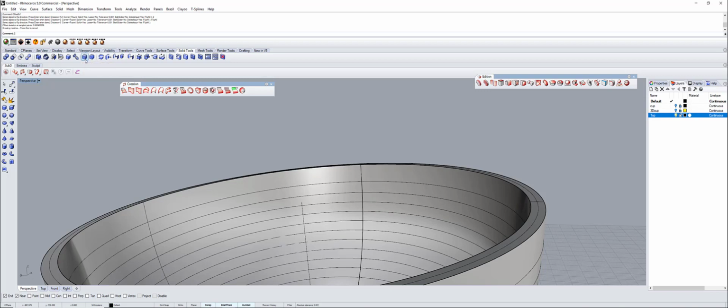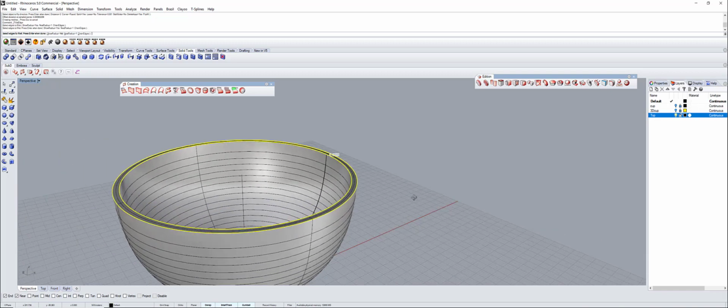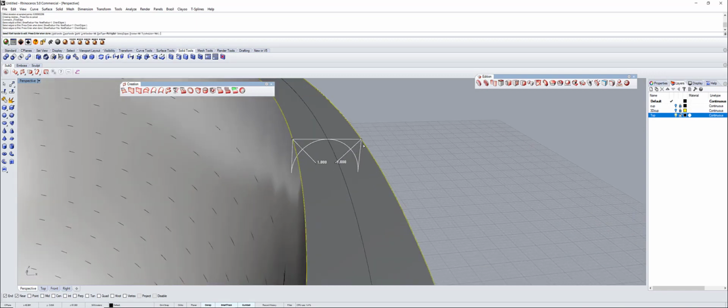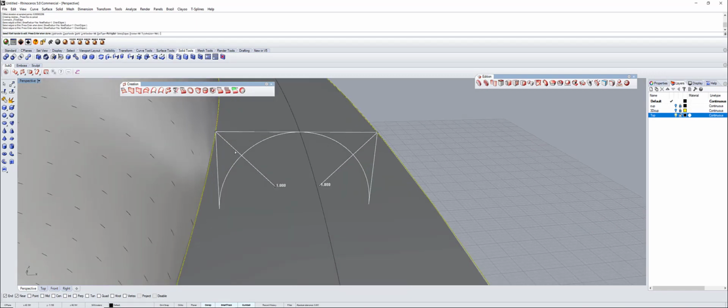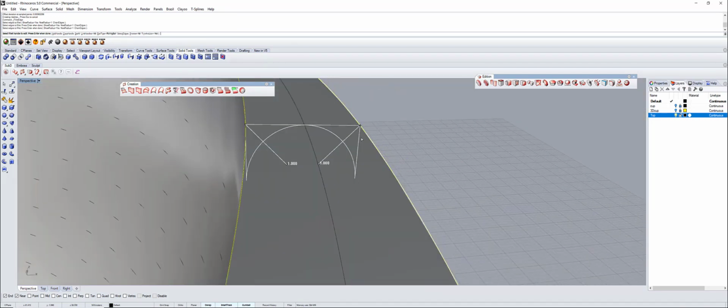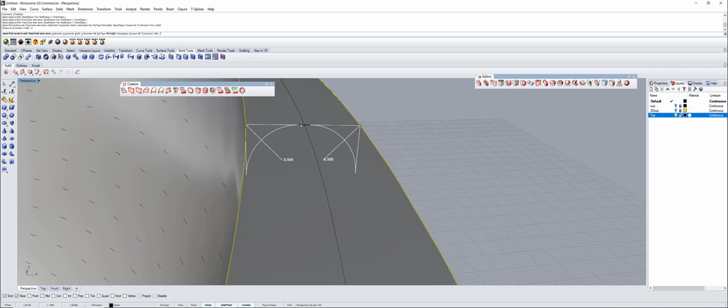So I'm gonna click on that one, and this is what it's going to do. It's going to round your borders. So you select this one, the outside, the inside. It's already telling me I have 1 millimeter, so I'm gonna press enter, and there is the size, how it's gonna go. But I think those two are crossing in the middle. So I'm gonna go to set all, and I'm gonna take 0.9 to see where they are. You see what I mean? There it goes.